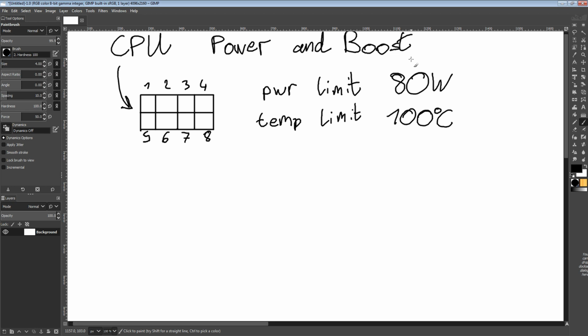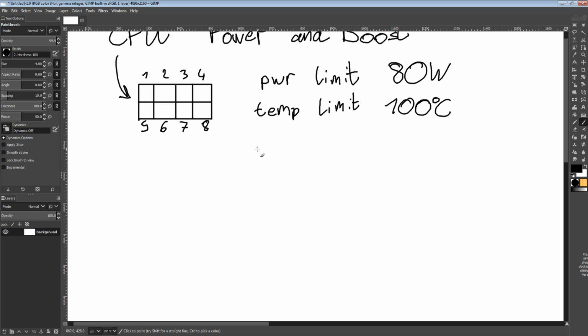If you push too much voltage, too much voltage translates into too much current, too much electromigration, dead chip. Or too much voltage translates into gate breakdown, dead chip. So you have different mechanisms for how voltage will kill the chip. High temperatures also increase electromigration. So you don't so much have a voltage limit as, if you're going really smart, a volt versus temp curve.